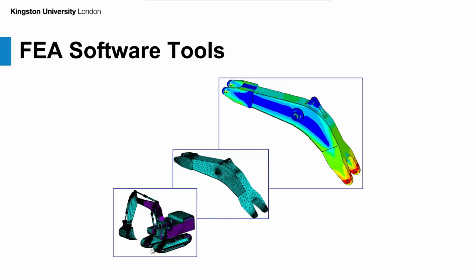The reason is that once we apply this discretization and make it into smaller pieces and study every single force, once we do it at the part level, and then put one part on top of the other and make the assembly at the end, those forces or changes in shape might have an impact on the other part as well, which is why it's really important that we do it at the assembly level as well.